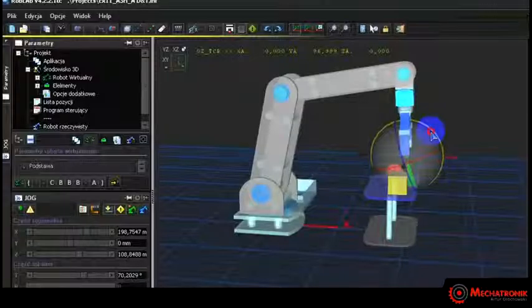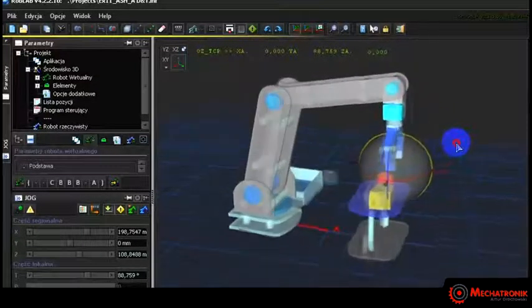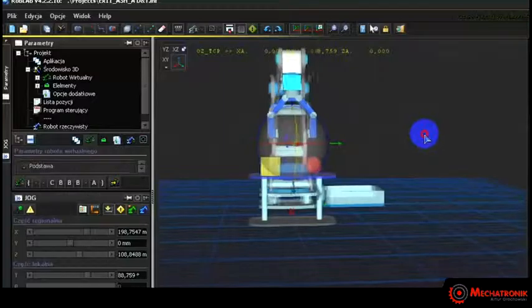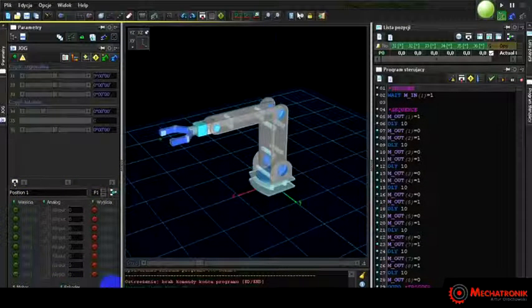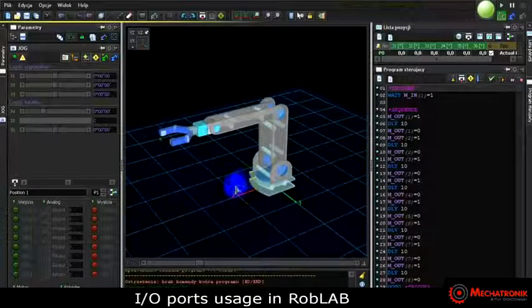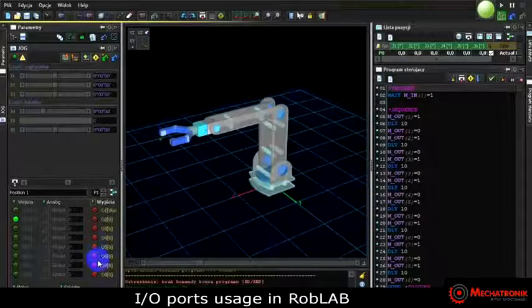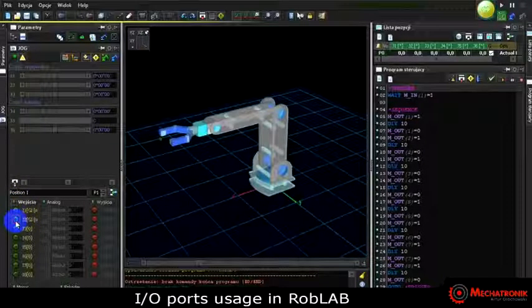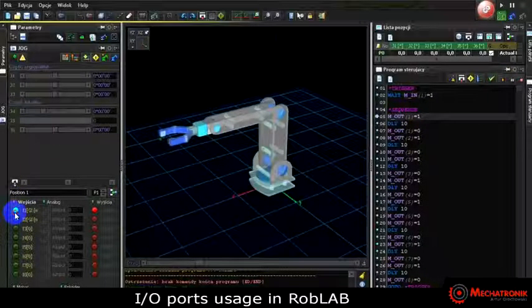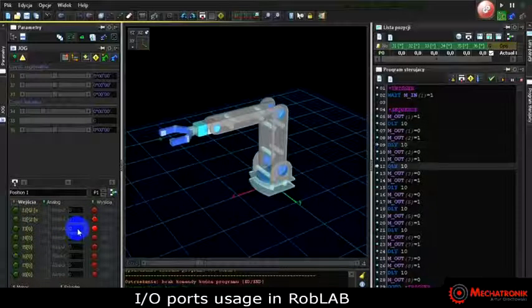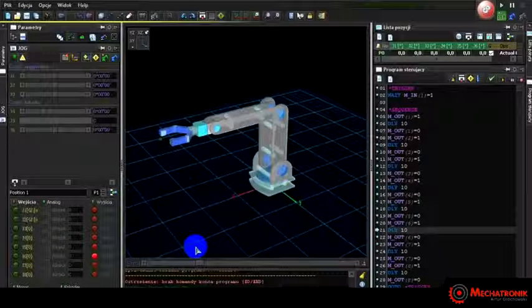As a result, the user can compare the pros and cons of various methods of programming of industrial robots, and write programs that use any of those methods, or use them in conjunction as required. The robot's controller and the application itself have an additional I/O module, that can be used both from the software level and manually. This additional functionality of the application enables not only controlling the robot's arms, but also cooperation between the robot and actuators, signaling devices, such as transmitters, valves, motors, push buttons, indicator lights, and any industrial sensors.